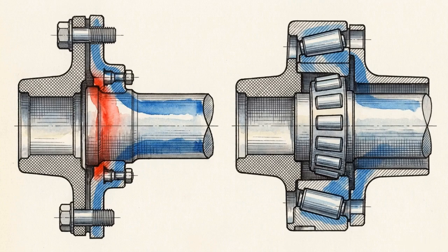The spinning shaft is forced to act as a weight-bearing beam, subjecting the steel to relentless, cyclical bending moments on top of severe torsional stress. The heavy-duty solution is the full floating axle architecture, which entirely redesigns the wheel hub interface. The wheel hub no longer touches the axle shaft. Instead, it rides on massive bearings mounted directly on the outside of the static axle housing tube.